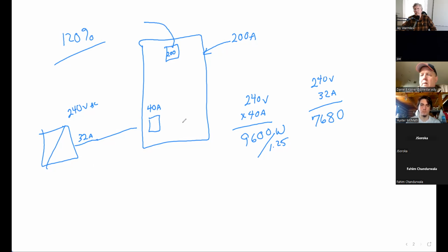So this is really the maximum size inverter that I could hook up under this system, doing a load side connection to a 200 amp service panel with 200 amps coming from the grid. As a result, when you start going out and sizing inverters, what is the most common size inverter you're going to run into? It's a 7.6 kW.